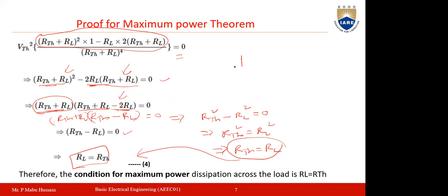If you take one simple circuit, here you have a voltage source, and this voltage source has internal resistance RS. So this is a practical voltage source. Now here you have the variable load, and this load will be changing. This load will get the maximum amount of power whenever the load resistance RL becomes equal to RS, according to the maximum power transfer theorem.